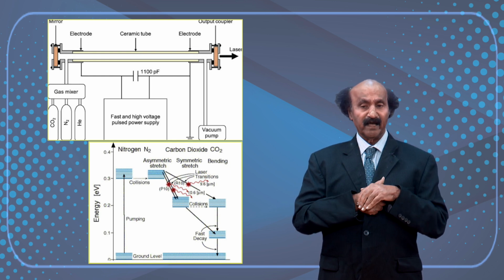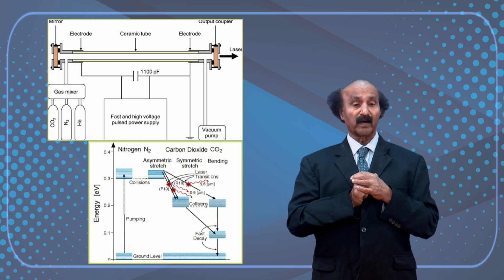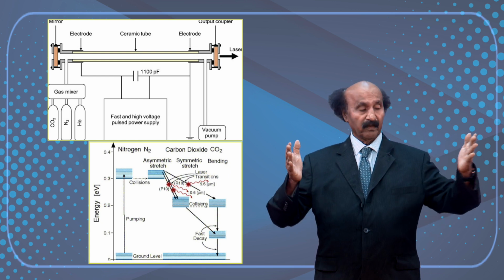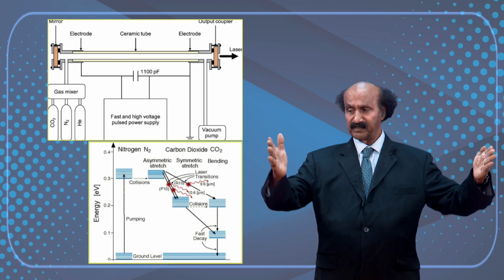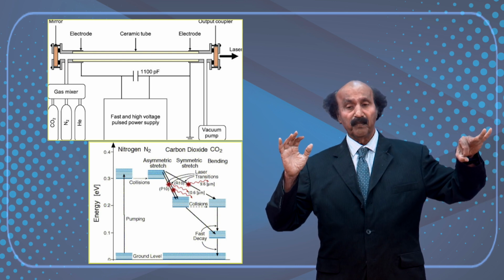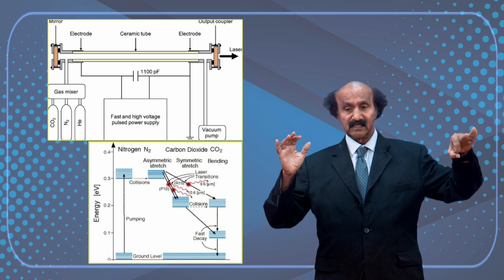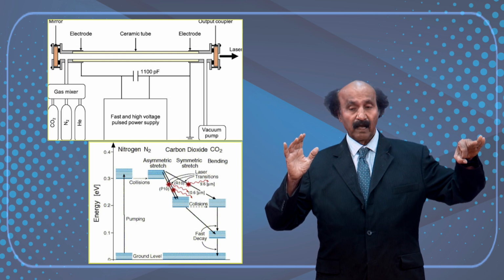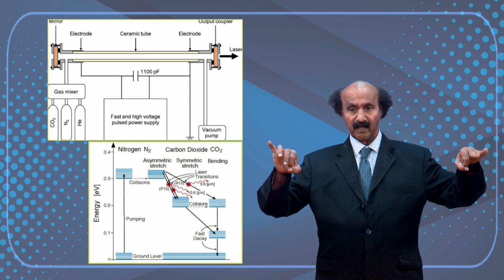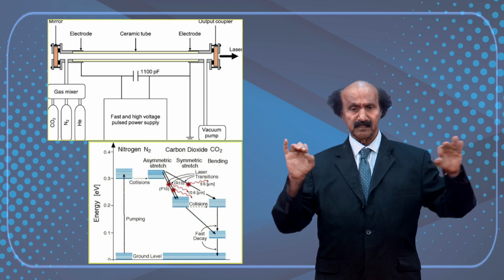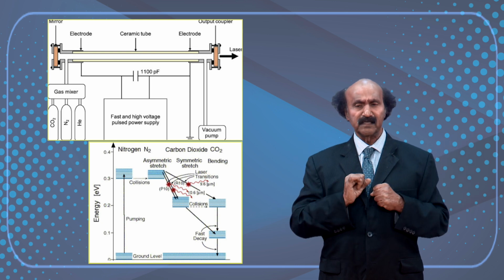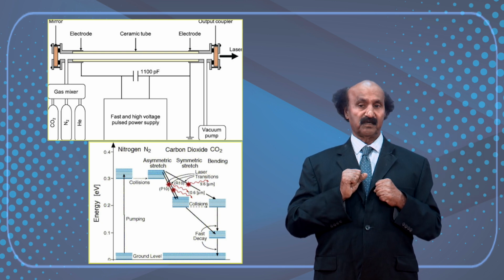There is something you should look at in what is given. Imagine that I have a zinc selenide mirror, and the whole tube up to this is complete zinc selenide, and this is a 90% mirror. If it is a 90% mirror, I will get only 10% of the light output at best.